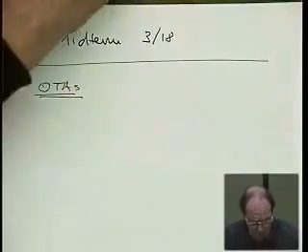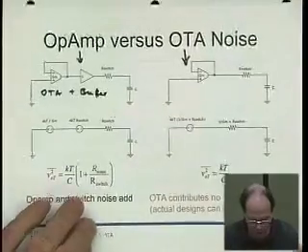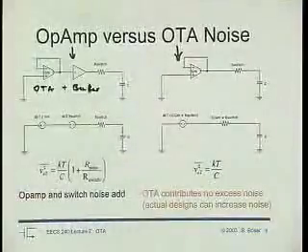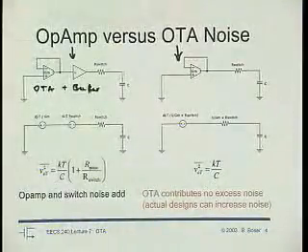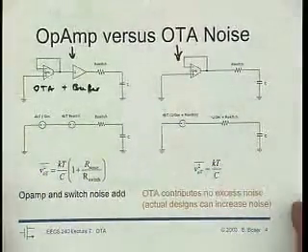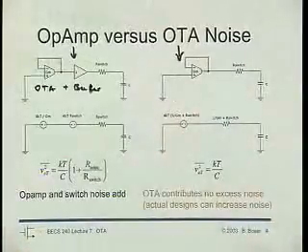When we looked at some of the differences and implications, one of the big things is that with an OTA we really can't drive a resistor, because the achievable voltage gain depends on the load. For practical values of resistors that we can build on an IC, that would be fairly poor, and we couldn't get reasonable gain except if we made these transconductors horrendous.